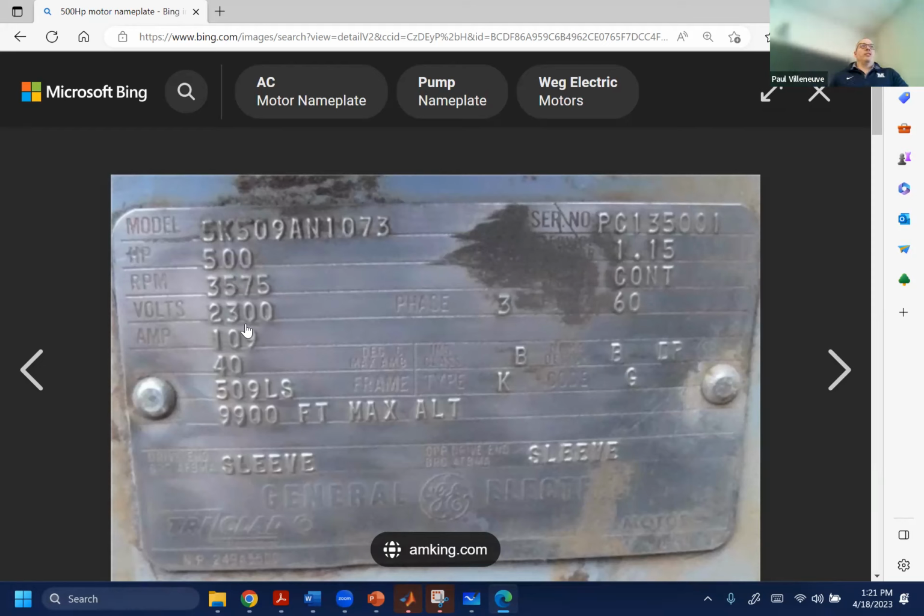It's not a huge deal to get a motor started that can run like that, but you've just changed the operating facility. Most industrial facilities want to keep everything at 480 or less. Why? Because you don't need any special training. Once you get medium voltage, you need special equipment and special training. You need more sophisticated electricians to test and more sophisticated operators to manage that equipment, because death is a lot more serious when you're dealing with medium voltage.